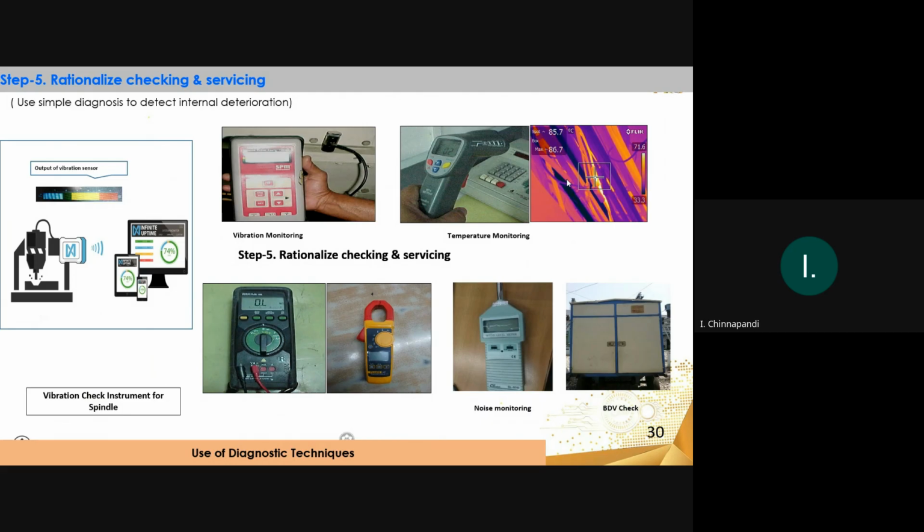We mapped the machine, identified the equipment, identified the component, then corrected it, made a standard, made a preventive maintenance plan, prepared a periodic replacement plan, and prepared a standard for checking. Everything is done. Now the equipment is working well. Now these are the diagnostic tools we incorporate along with the machine so that it can give an indication before it fails.